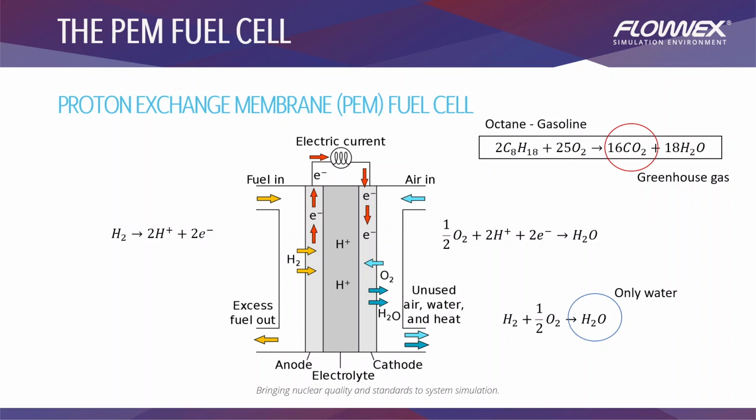This means that it can start up quickly because less warm-up time is needed. It also has a high power density and is low in weight. The fuel cells used in electrical vehicles, for example, are most commonly the PEM fuel cell. Fuel cells transform chemical energy through an electrochemical reaction of hydrogen and oxygen into electrical energy.